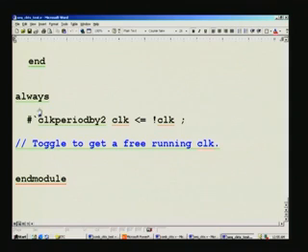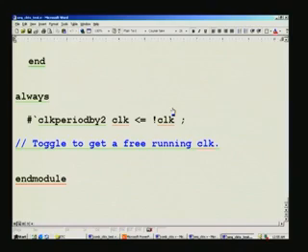Here there is no begin, no end, because it has a single statement, and notice this, the clock is inverted, and this symbol is used for assignment, not the equal to, as I said before, an always block must always have this symbol. In assign and initial blocks, etc., you can use that equal to. Are you all clear with this, right? And that is how it will toggle, right. Finally, for a module, you need a matching end module as such.